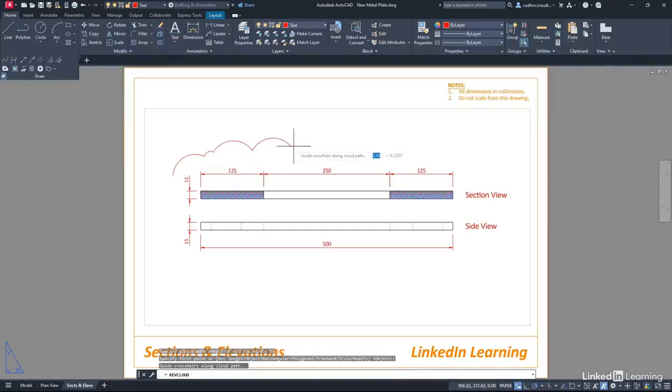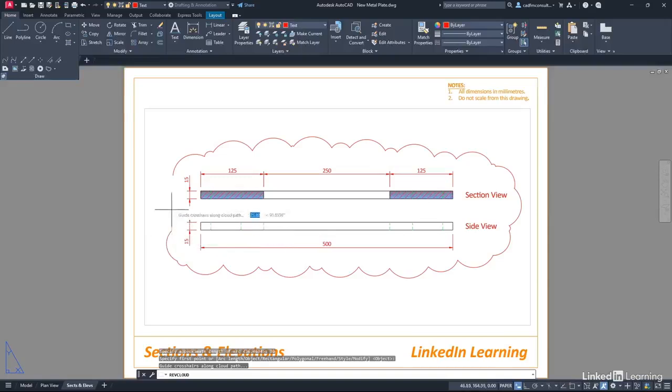So I'm just going to click around. Can you see? And as I drag, the rev cloud appears like that. Keep coming around. And it'll just try and get them all to about 30 long. Keep coming around, and when I get towards the end, it closes it for me. Hit escape a couple of times just to come out of any commands or any selections there.